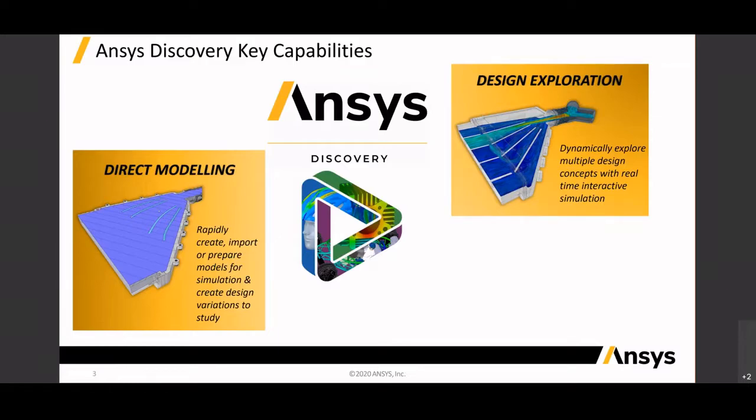And obviously what a GPU offers is typically a lot of available cores. On your typical CPU, your PC, you might have 4 cores, 6 cores, 8 cores. Whereas on a GPU, it's pretty common to have 500, 1,000, 2,000 cores. So that's giving the sort of expansion of processing capability. And because simulation is a pretty good process to parallelize, 1,000 or 2,000 cores is a great environment for speeding up significantly the runtime results to be returned.